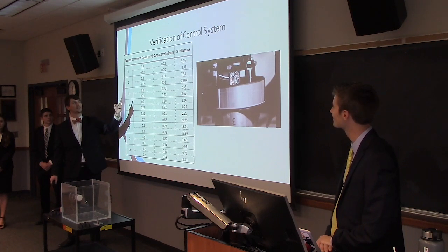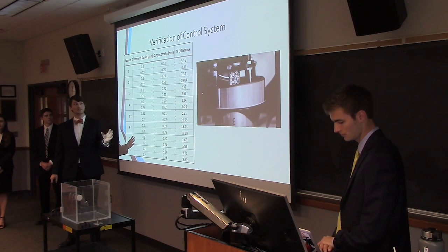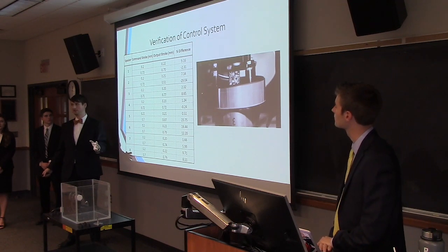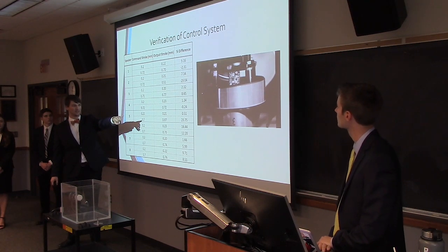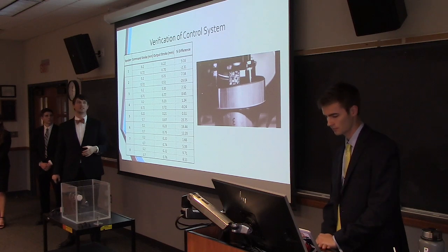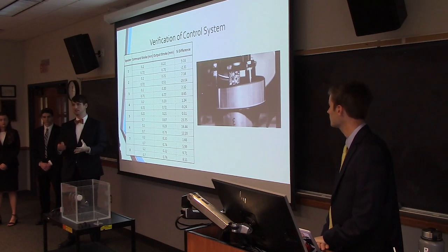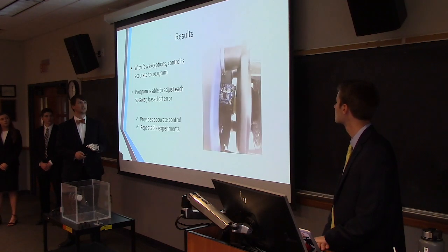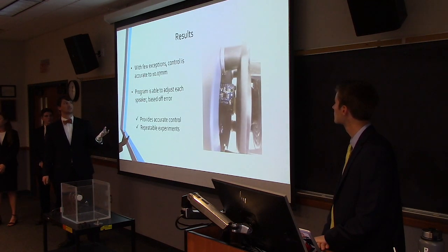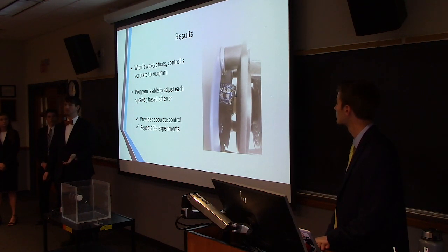A command stroke of 0.2 and an output stroke of 0.22. The thing is, you have to remember this is in millimeters. So even though that percent difference seems significant, it's actually fairly close and fairly accurate. Now there are exceptions. You can see there's a negative 29% difference and a 23% difference, but we're fairly sure this is because of the accelerometer not being calibrated precisely, or just the speaker operating very strangely. Overall though, we're able to conclude that with few exceptions, we're accurate within about plus or minus 0.07 millimeters, which is a huge improvement over the previous system.